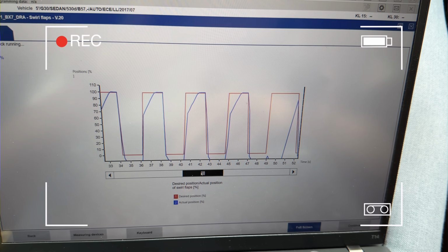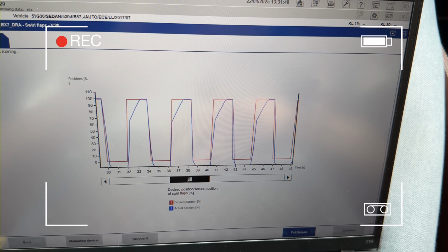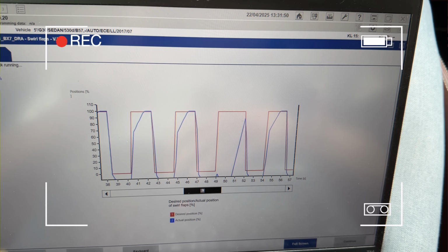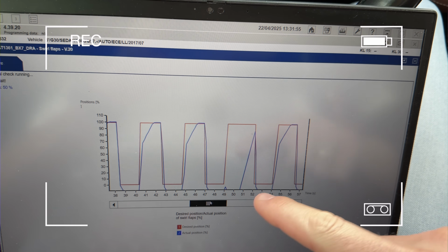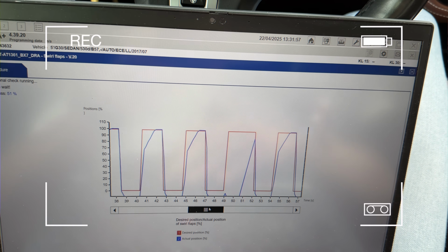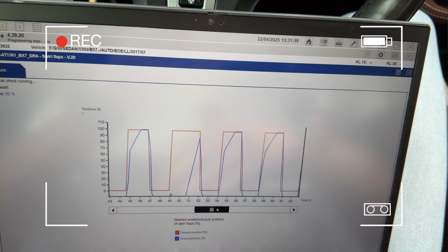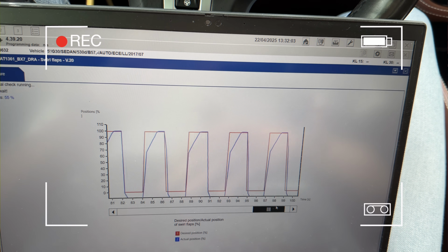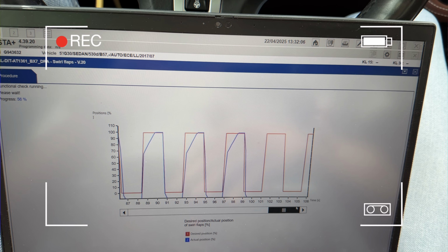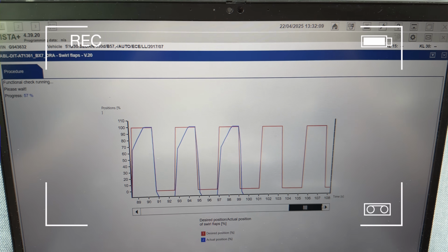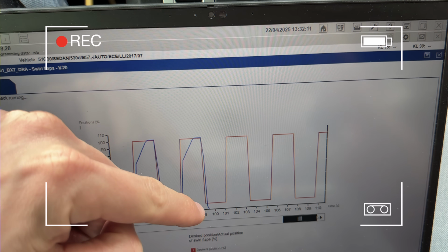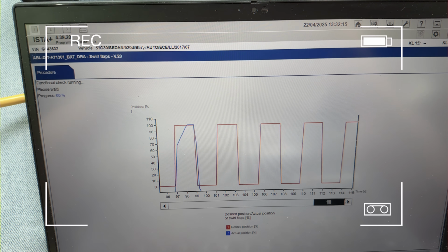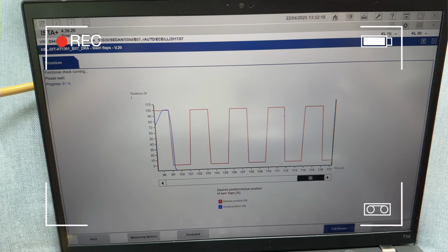And one more afterburner. Basically, the swirl flaps are working again. You can see the pattern is not as it should be. And over here, you can see they failed to open or close completely. And I'm just continuing to monitor those. So yes, they are working somehow, but up over here, and again it's running. You can see they were closed and they are not opening again, so they are stuck again somewhere. So it is definitely not a bueno situation.